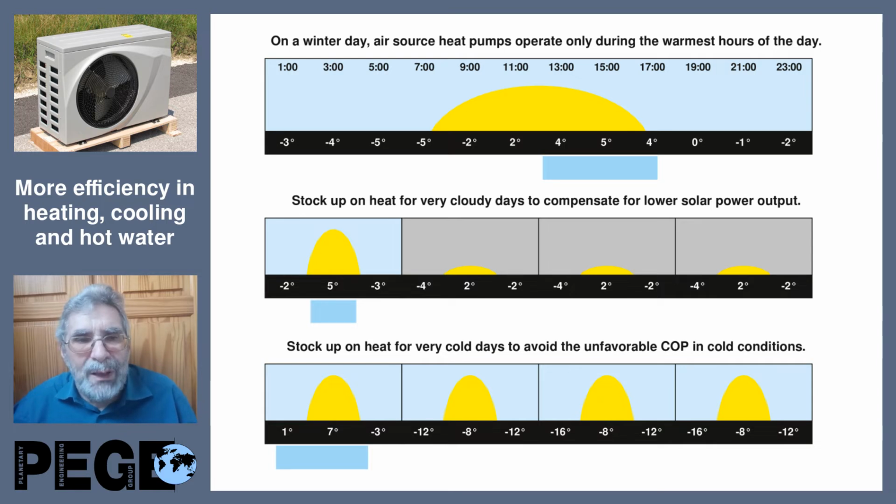And so we can maybe have with these systems a higher yearly coefficient of performance than a usual water-to-water heat pump. This we want to achieve with this patent, that we can use air heat pumps really everywhere, because the big disadvantages of the air heat pump are away with the low temperature heat storage.